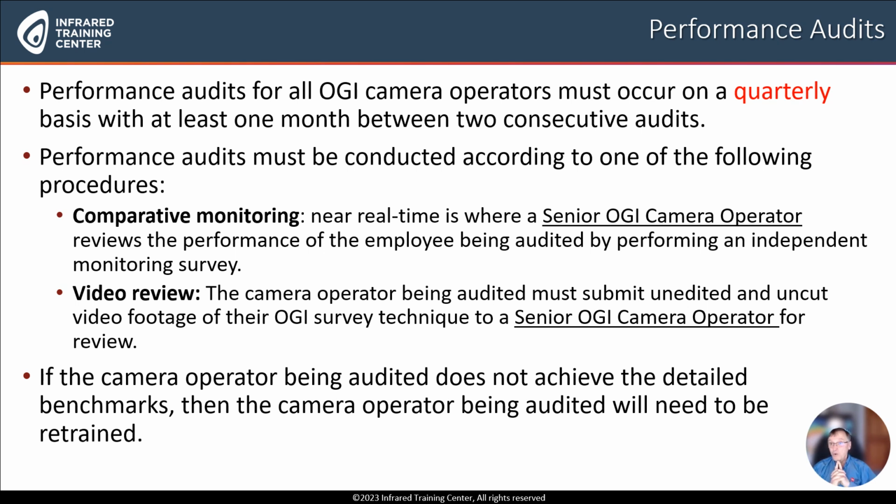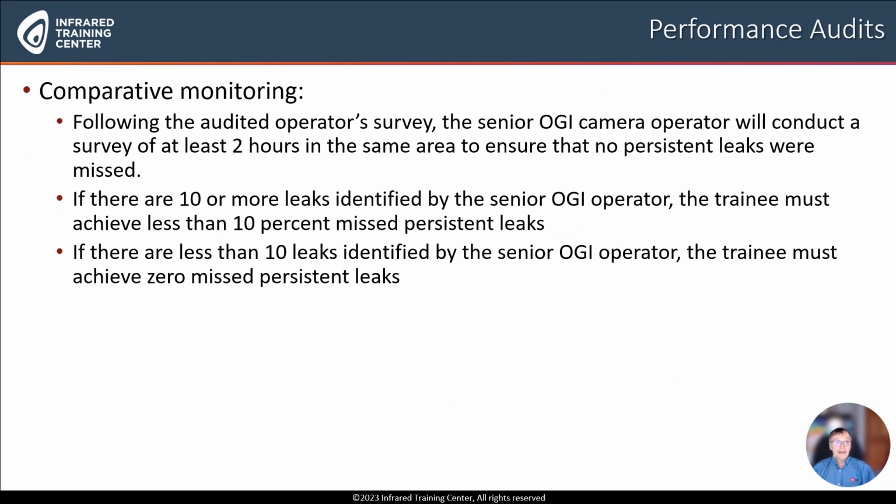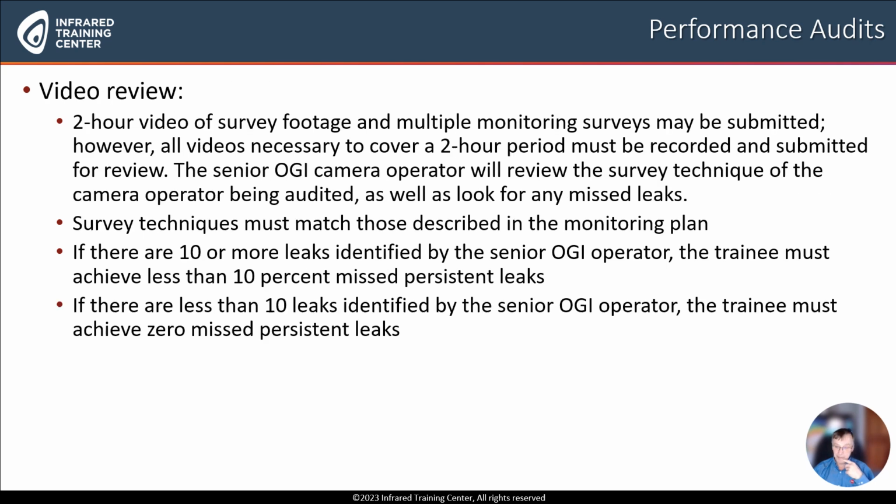And so again, quarterly audits for everybody. If the camera operator does not achieve the detailed benchmarks, then you have to go ahead and be retrained. Now, the comparative monitoring: a senior OGI operator will conduct a survey of at least 2 hours in the same area to ensure that no persistent leaks were missed. And again, it's a 10% leak or less than 10, you have to find them all.